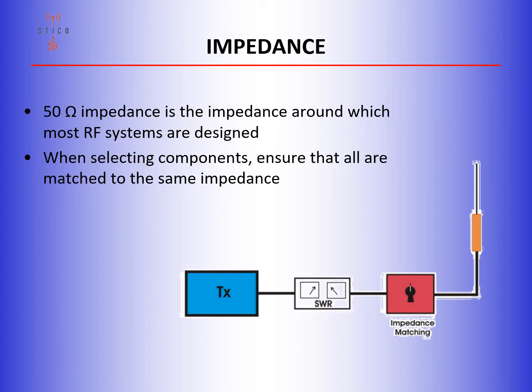Input impedance. Impedance is a measure of resistance and reactance. What is important for you to remember is that in general, today's transmission systems are designed to work at 50 ohms. The transmitter, the feed line, and the antenna should all work together. If the impedance of any of these three things is different, the result is loss in the form of heat or reflections.